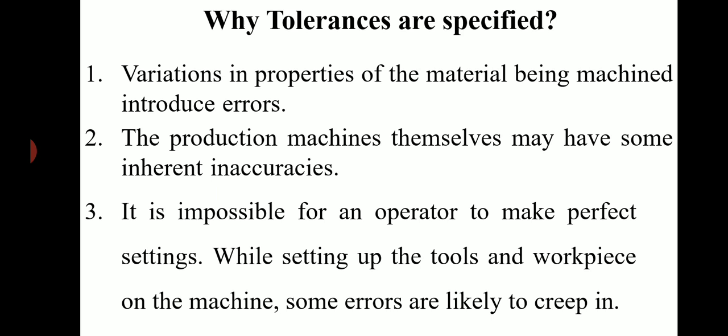Why does tolerance need to be specified? Variations in properties of the material being machined introduce errors. The production machines themselves may have some inherent inaccuracies. It is impossible for an operator to make perfect settings. While setting up the tools and workpiece on the machine, some errors are likely to creep in.